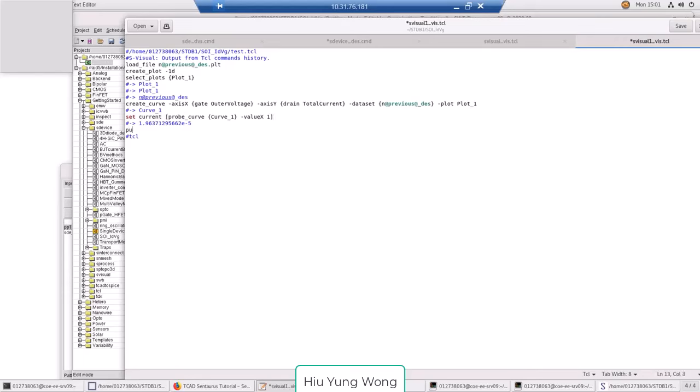And what I'm going to do is to type puts, another command, to print it in the log file. DOE colon current, for example, I call this current, $1 current, right? So this is a new language. I don't expect you to know it immediately, but you know approximately what I'm doing. When you need it, you just Google or ask me. So basically what this is doing is that it opened the file just like GUI, and I probe it, it returned the current value, and it becomes this variable $current.